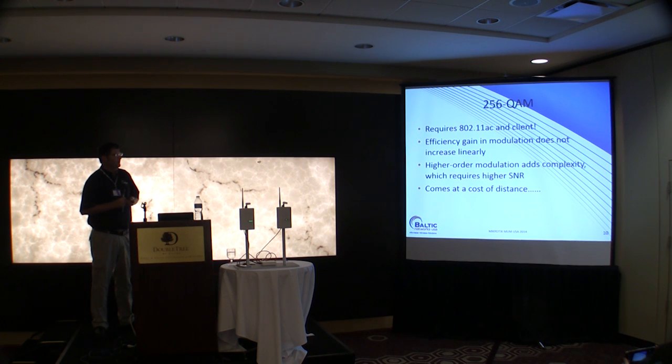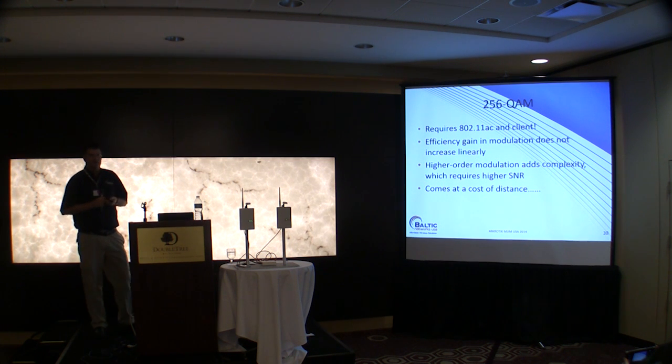So it is a requirement. There's an efficiency gain, and you'll see in another slide here that it's not linear. As we increase the QAM modulation and go to 512, 1024, you're not going to increase the efficiency as much as you would expect. It does require a higher signal-to-noise ratio in order to stay working, and then, of course, it comes at a cost of distance.